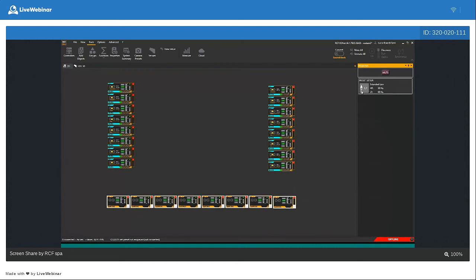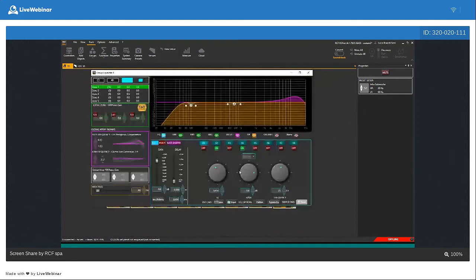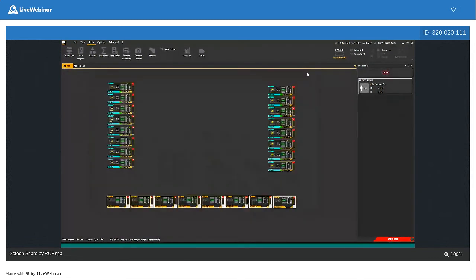If I am not wrong, our crossover was at 60 Hz, so let's select the preset S2 from 20 Hz to 60 Hz. So our system will play with subs between 20 and 60 and with the tops from 60 up. But at this moment, all the energy is concentrated in the center, so it's not a good thing.